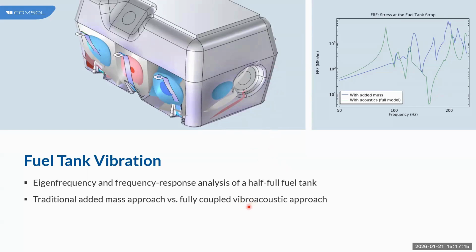One is the traditional added mass approach versus the fully coupled vibroacoustics approach. In the plot that you see here at the top rightmost end, the two methods show significant differences. It also highlights how important it is to accurately capture the vibroacoustic behavior when you are going to predict the stress or fatigue life of fuel-filled cavities.